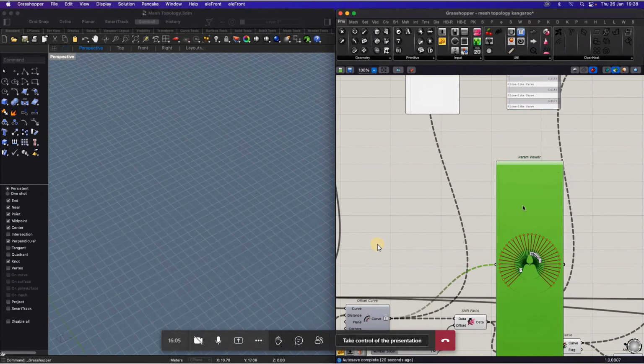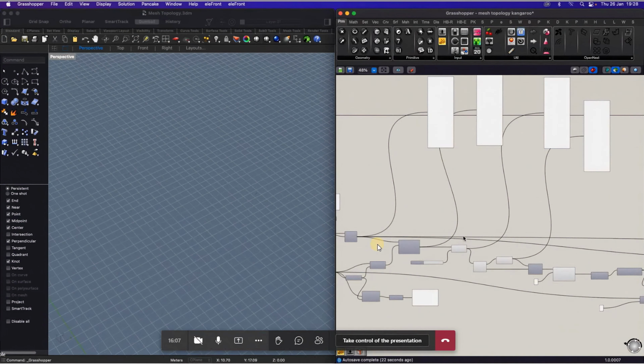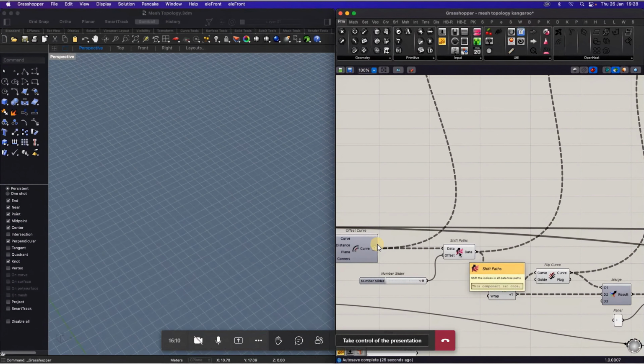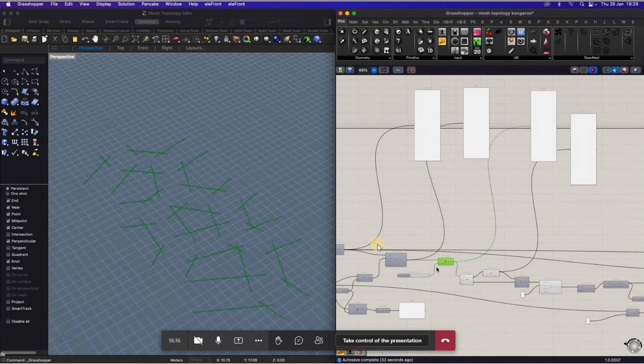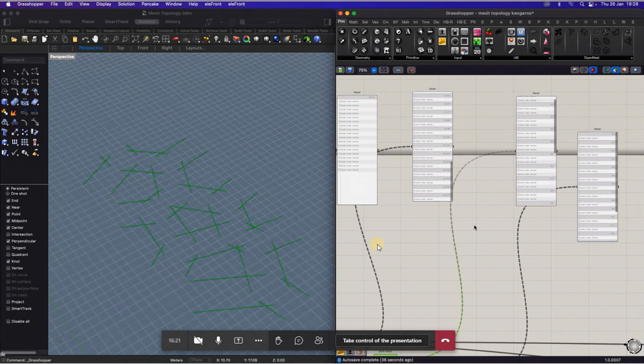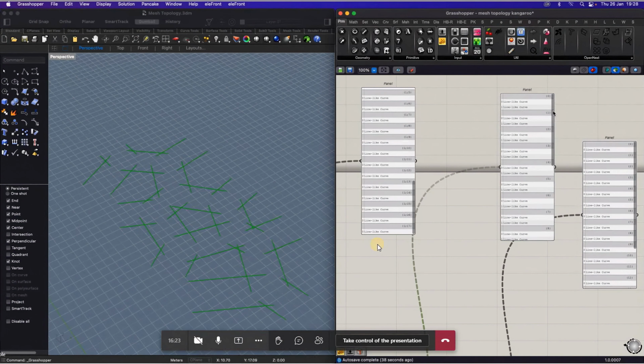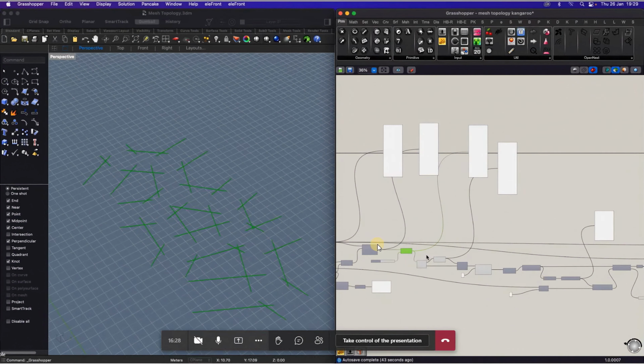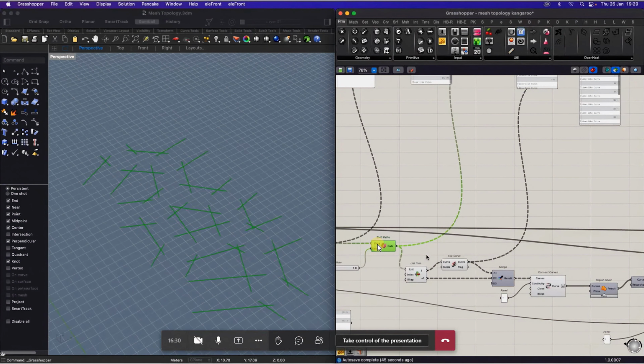So shift path, which sounds like something you may have to do in Dynamo as well, pushes those two lists together. I'm sure it's much more scientific than that. But basically, it takes the list 0 and the list 1, and whatever was the item 0, both of those lists get combined together. So then you can work on those in pairs of all the curves. Yeah, that's called transpose in Dynamo. Is it? Okay, great.